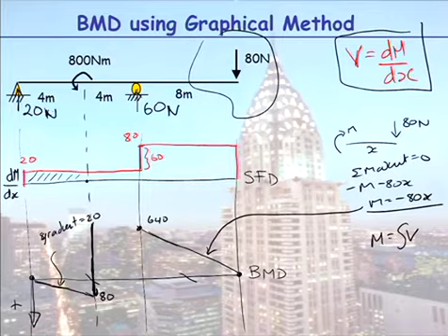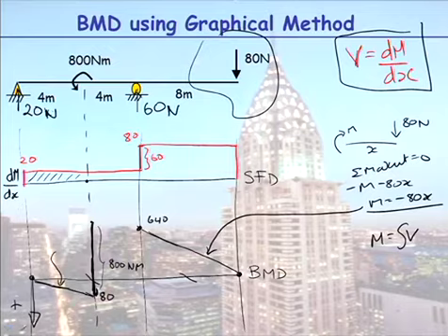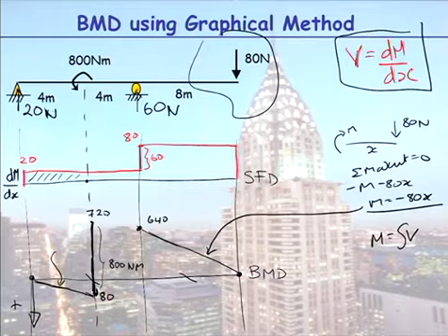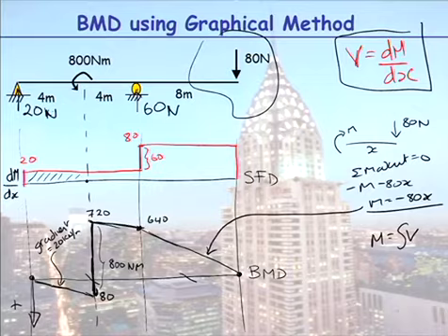Now, when I have this step up in my bending moment diagram, it's stepping up a total of 800 newton metres. Thus, it's taking me to a value of, and because I've written that there, I'll just move that across, so it takes us up to a value of 720. And I'll write over here gradient, again, equals 20. And my shear force is constant again, which means it then continues to slope down. And there is my bending moment diagram this time.